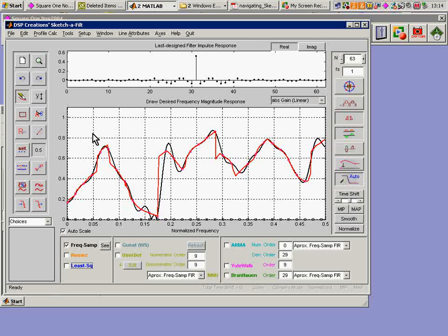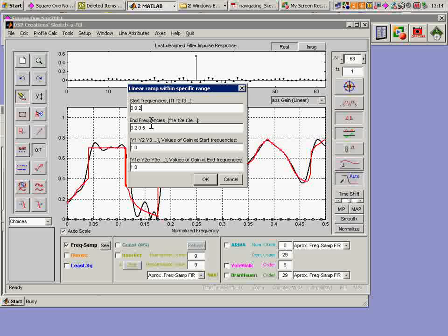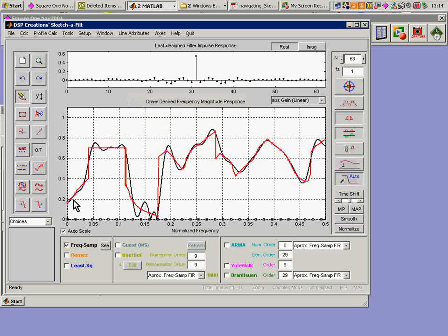Now we might want to change the shape of this target profile in some sort of way. I'm doing a right click in rubber band. I might want to set this to 0.7 units high, and there I go, and I'm able to do that. I can do various careful changes of the vertices of the straight line segments making up a profile by typing them in here. This then allows us to move away from sort of whimsical designs to things which are actually following some specification that the designer may have to go to, or the designer may wish to go and write an equation for this target profile.